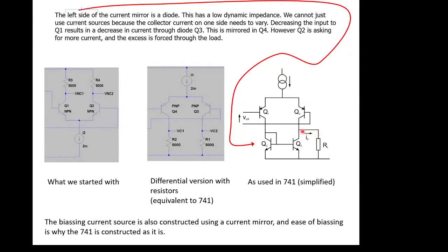And that's how we turn it into a single-ended thing. This is fixed current, and it's defined by the voltage across here, which is defined by the difference input here. That fixes a current through here. This one tries to match the current, but it obviously can't because this transistor is going the other way. If this one's asking for less current, this one's asking for more current, and vice versa. And the only place that spare current can go is either out of here or in from here.